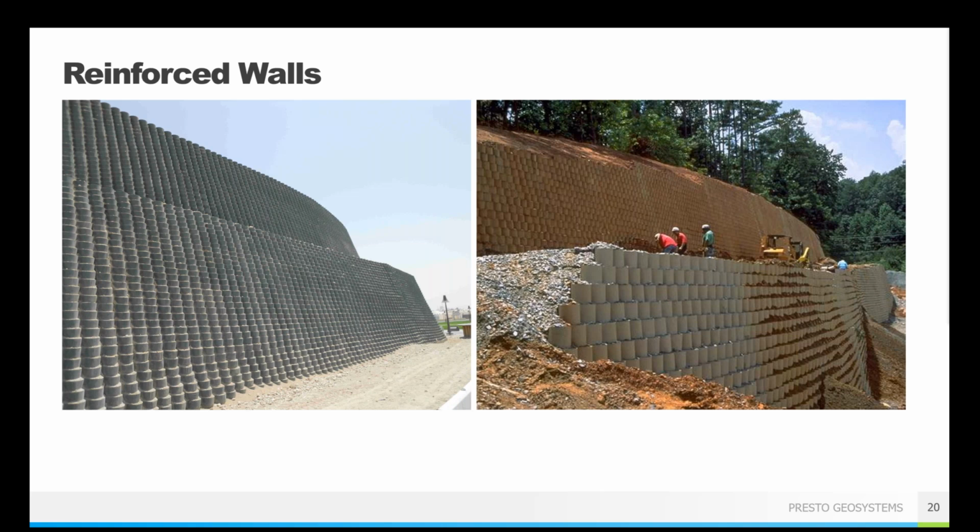You get the idea. So if you do have an incredibly high wall, you would need a lot of excavation to put that geogrid reinforcement in place. So if you do multiple tiers of shorter height walls, you can have shorter reinforcement lengths, still achieve your total height that you need for the wall, your total overall required height, without having to do excessive amounts of excavation. So something to keep in mind if you've got that sort of flexibility on your project site.